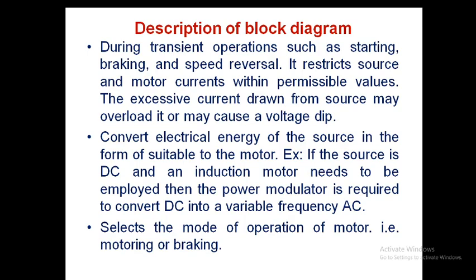It may be forward motoring mode, forward braking mode. You need to adjust the firing angle to get that forward braking mode. Reverse motoring mode, how to get that? We need to reverse both voltage and current, to get them negative or reverse. For that, how your firing angle needs to be adjusted, which type of converter or power modulator you need to use, that we will see. So next one is